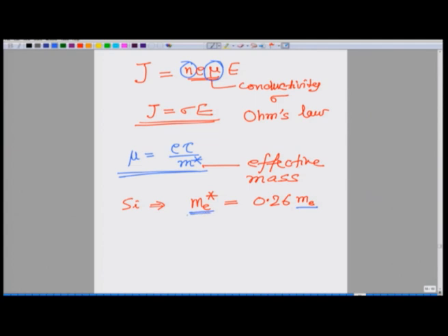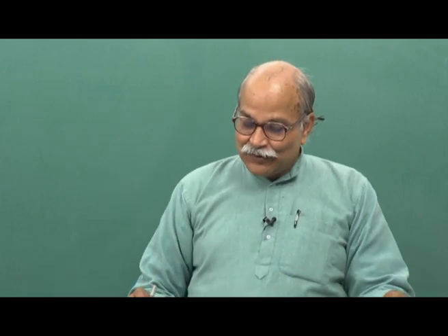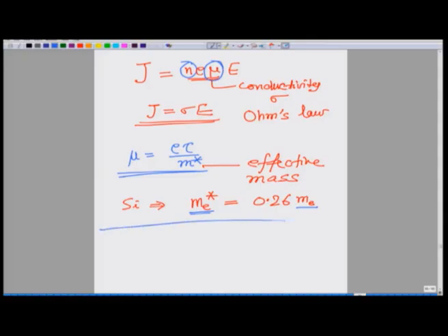So, effective mass has decreased, that means this crystal is helping in motion. So, that effective mass has to be used here. And so, the current is proportional to the charge carrier concentration and also to the mobility, and this mobility will depend on the effective mass.